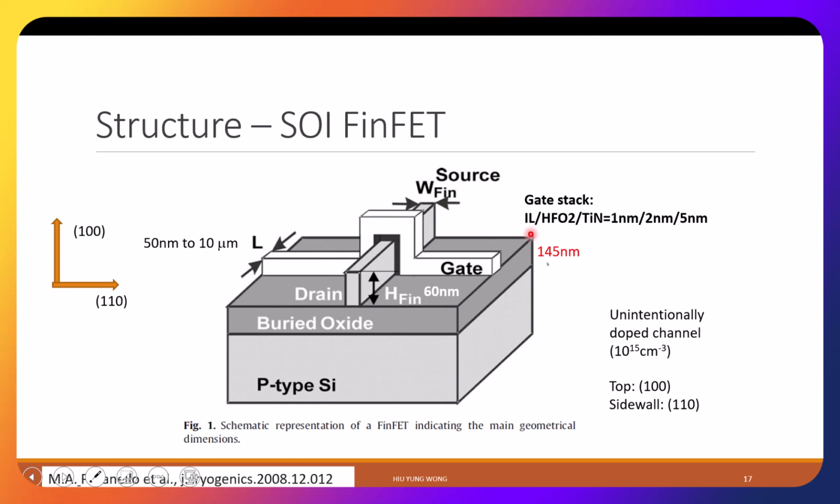But what I want to talk about is the gate stack. Just now he mentioned hafnium dioxide. So nowadays, what is a state of the art FinFET like? Not everyone uses the same thing, but it's similar, right? You have the silicon here. You first have something very thin, only 1 nanometer. Nowadays, it's even less than 1, maybe 0.6 nanometer, 6 angstrom.